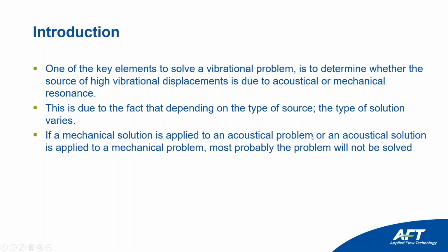So you cannot change supports if you have acoustical resonance, because changing the location of the support is an external solution, and you need an internal solution. On the other hand, you might have mechanical resonance, and it's more appropriate to have an external solution, like changing the rigidness of the support or the type of support you're using, instead of trying to solve it internally. So again, this is the basic thing. You have to determine whether you have an acoustical or mechanical problem.